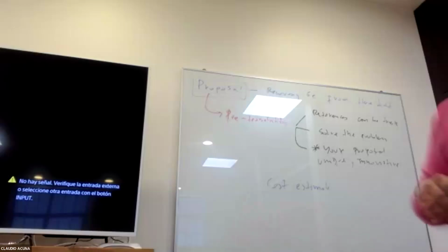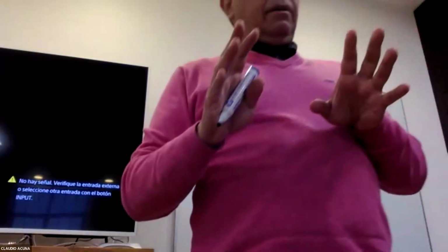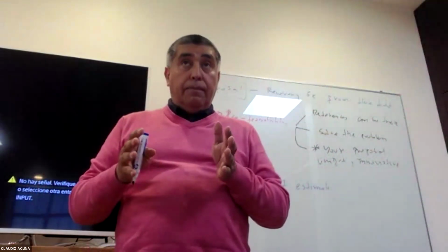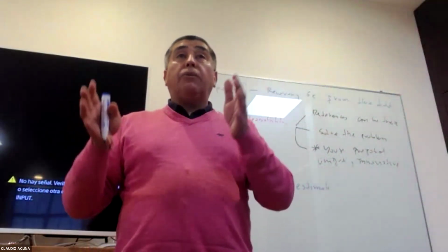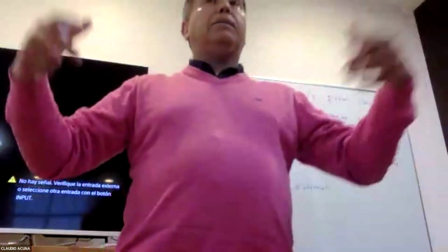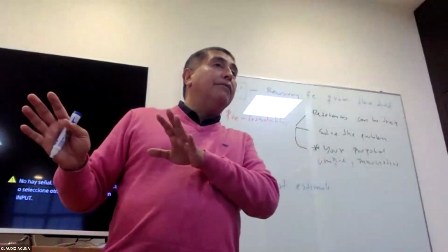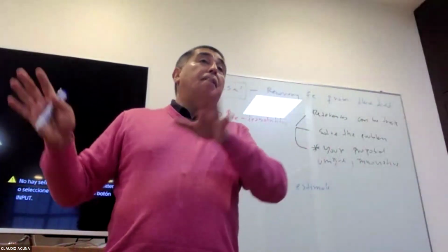The capex, you don't need to estimate the capex for everything. You estimate the capex for the more important equipment. That will be an agitator reactor. So this agitator reactor, you can estimate the capex. It will be 500,000 depending on the amount that you want to process. And then the rest of the equipment will be 3 times. And for the rest of the aspects of the plant, civil work is another 3 times. And that's it. So this is a $5 million project.